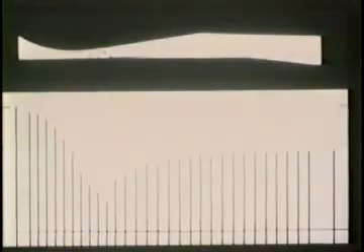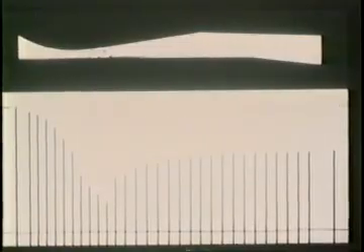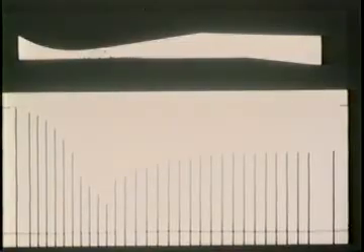So is the pressure distribution, because at first the pressure is decreasing, and hence the velocity is increasing in the diverging channel. After the shock wave, the pressure is increasing, and the velocity is decreasing in the same diverging channel, showing subsonic flow. The supersonic region ends at the shock wave. Because there is no upstream influence in a supersonic region, the Mach waves are steady. But the shock wave is not.